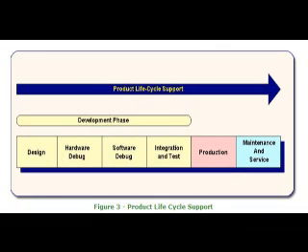As the acceptance of boundary scan as the main technology for interconnect testing and in-system programming, ISP, has increased, the various boundary scan test and ISP tools have matured as well. The increased number of boundary scan components and mature boundary scan tools, as well as other factors that will be described later, provide engineers with the following benefits. Easy to implement design for testability, DFT, rules. A list of basic DFT rules.